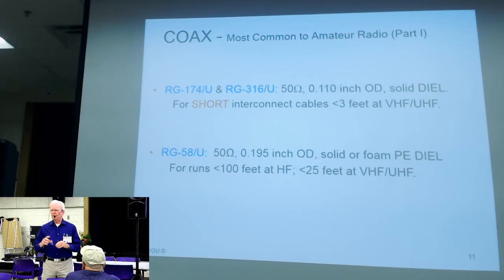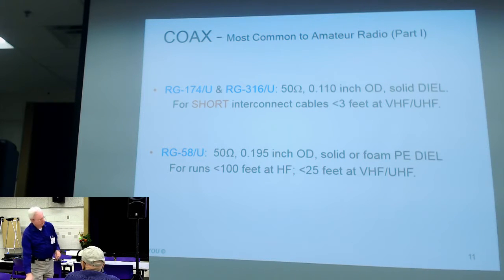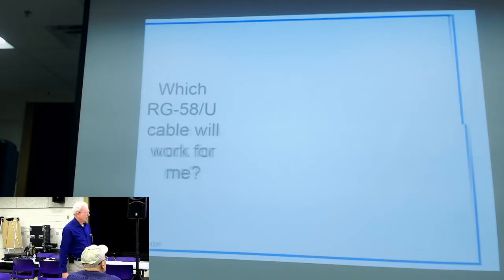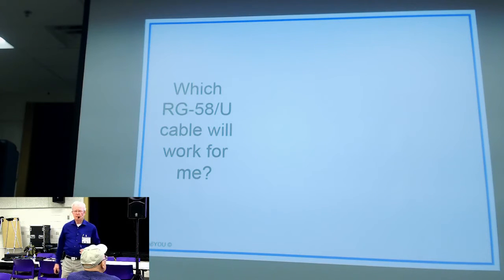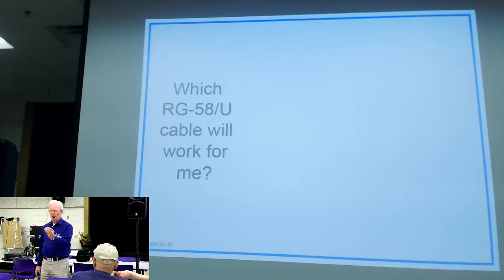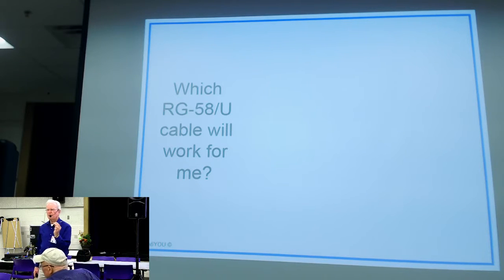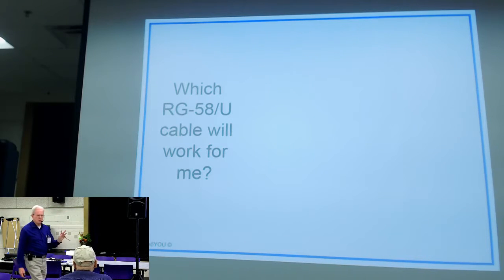Which RG58 should I buy? Well, this is great for HF, by the way. I use this, a 50-foot run for HF. This is fine. If you're only running 100 watts, it's good cable. You don't want to spend much.